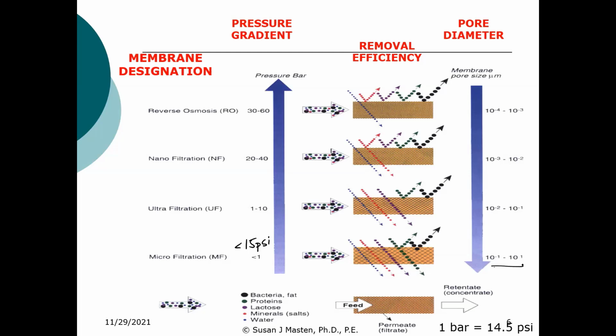And here, if you look at what we're removing: bacteria. We can remove Cryptosporidium oocysts. We can also remove Giardia. So most of your backpacking filters are really the low end of microfiltration, and we typically refer to these as coarse or tight. So tight being the low end and coarse being the larger end, and this is true with any of these filters.